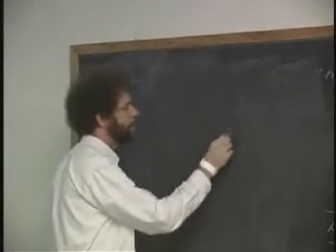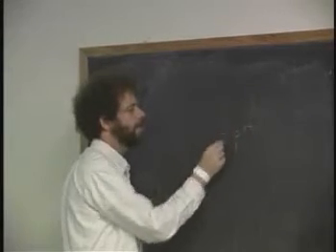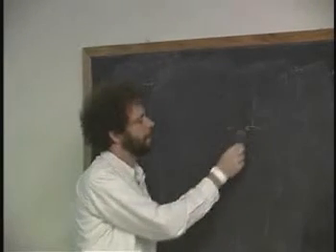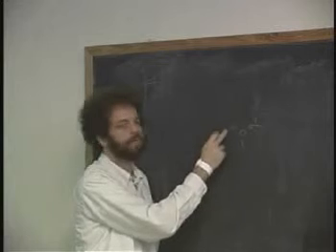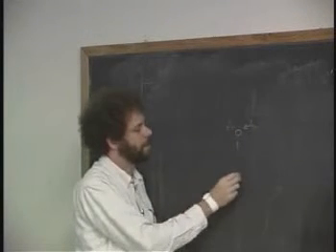Well, when's that going to be true? I'm going to want to propagate the carry when? If it's 0 and 1 and a carry comes in, should I propagate the carry out? Yes. 1 comes in and a 0 and 1. Should I propagate? 1 plus 1 is 0. Yeah, okay, so that's one case.